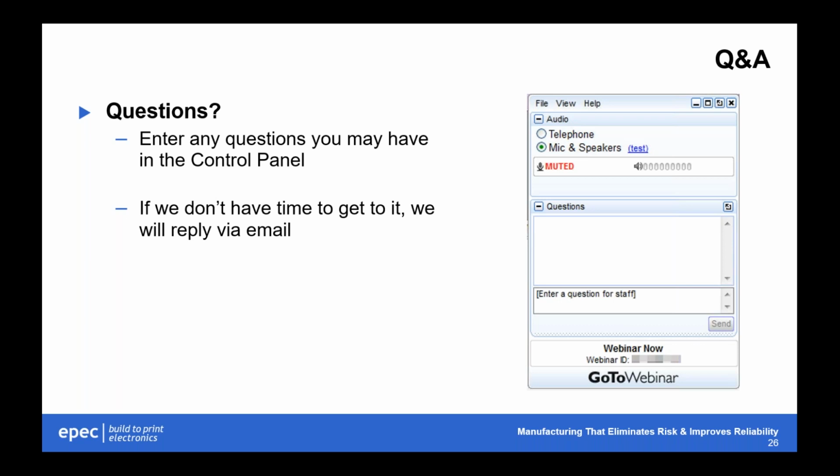For zip connectors, the material is always polyimide. The thickness is going to vary depending on what's needed to meet the zip connector specification. Typically, it's going to range from 2 thou to 8 thou in thickness. Polyimide is also the preferred and only used material for this application.